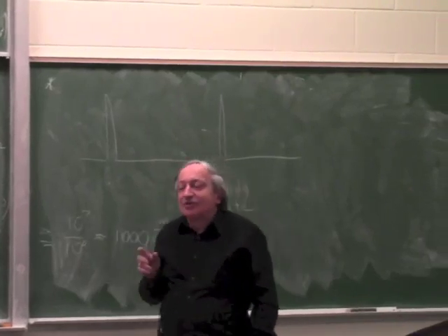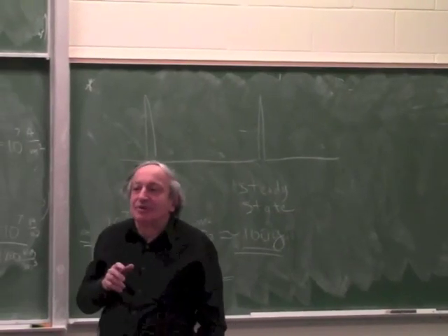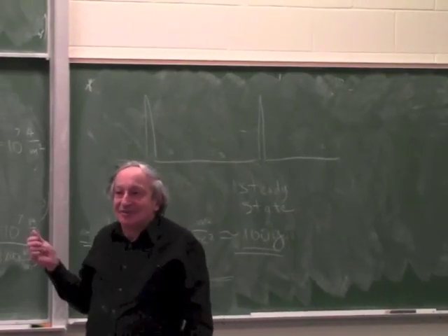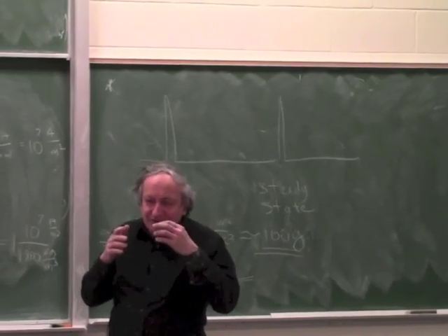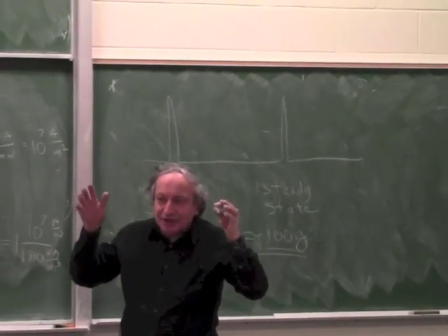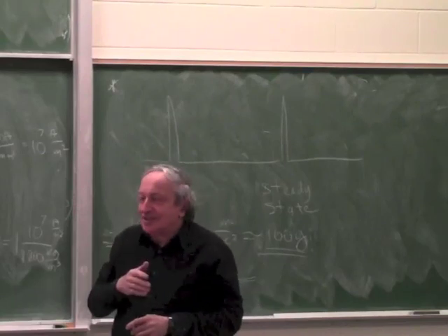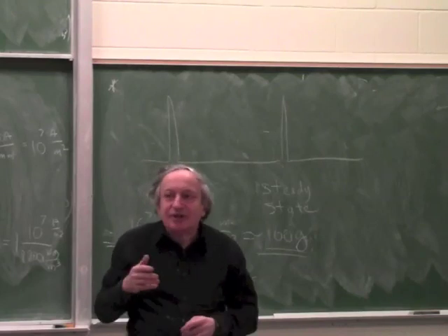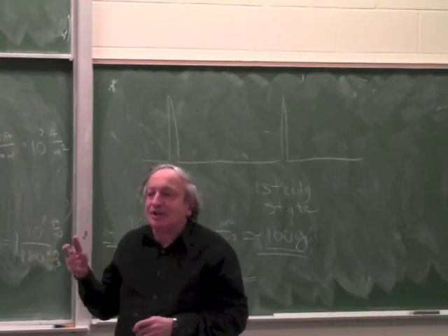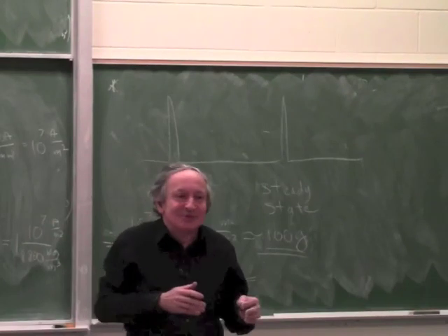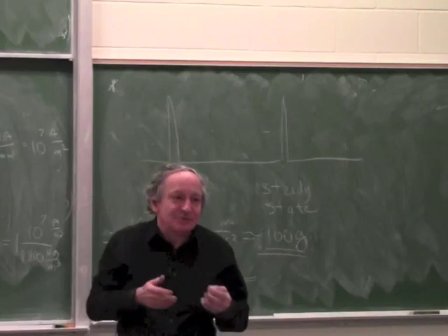By the way, I cannot make a coil without impedance, because a coil without impedance will also generate no force, because they are theoretically linked. If you think about it in a bigger picture, the force is the derivative of energy with respect to distance. And the energy in a coil is 1/2 L i squared. So if I can make a coil with no impedance, it will also make no force, because it will have no L. And then the derivative of the energy with respect to distance will be 0.